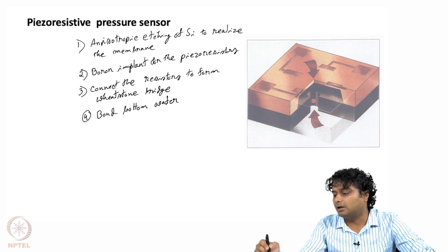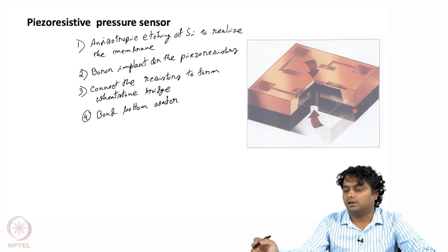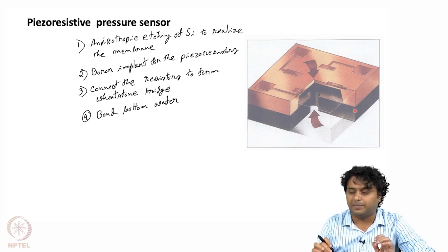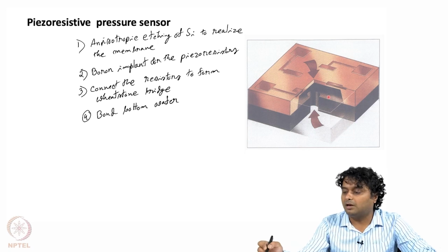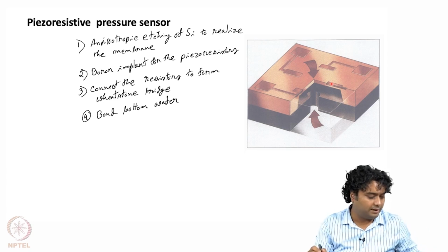We cannot etch material from inside, so first we make this wafer, then we separately make the other bottom wafer, and then we just join them together. You can think of it as clamping two wafers together, with a vacuum or air trapped space in between, which will be like trapped gas, and then the top thin side acts as a membrane. Now we will discuss how we can make it.